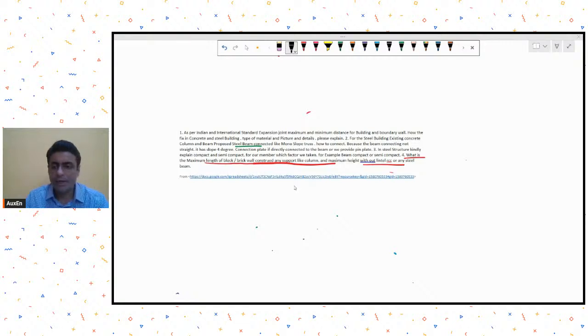But it gives you a good explanation. There are some good figures given about the slenderness ratio that you can have for your brick wall, and about the thickness that you need to maintain for your brick wall for a given height. All those things are given in that code. You may try to search for it, and you will get a good idea. From that you can calculate till what height you can have a brick wall without providing a horizontal tie or without providing vertical columns. So that code will give you a good idea about that. I'm not able to recall its number right now.